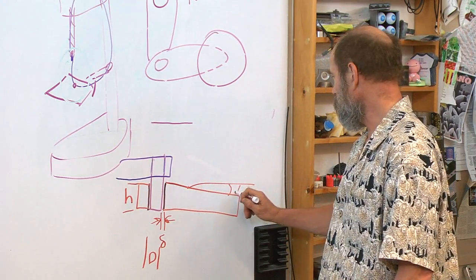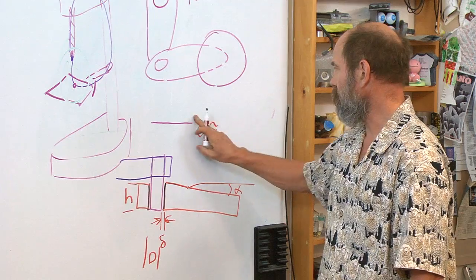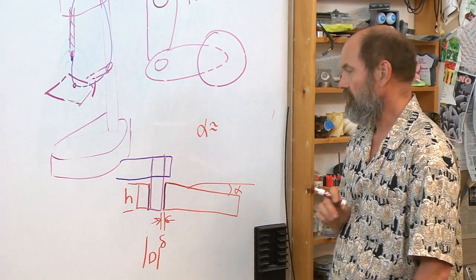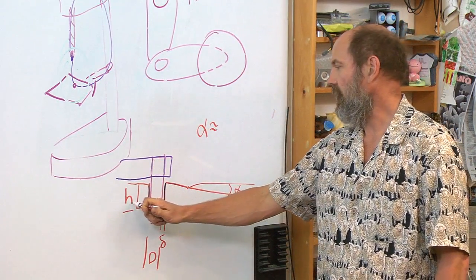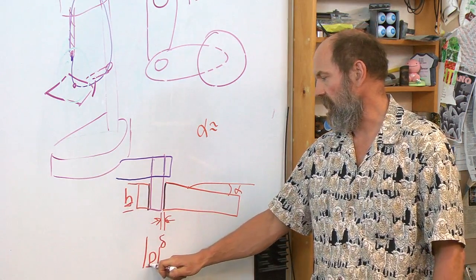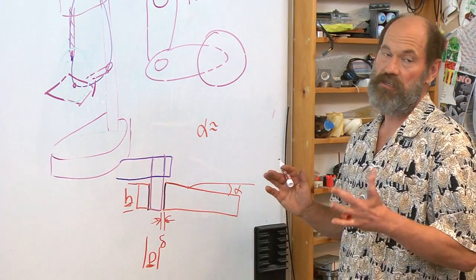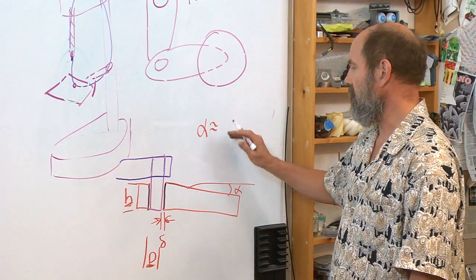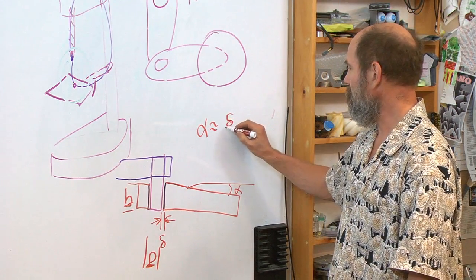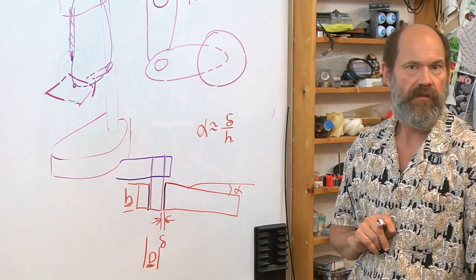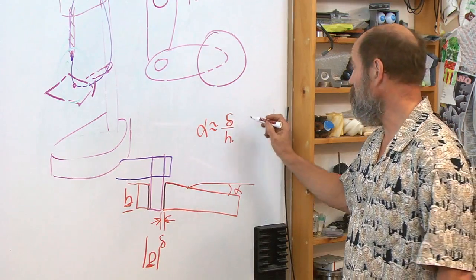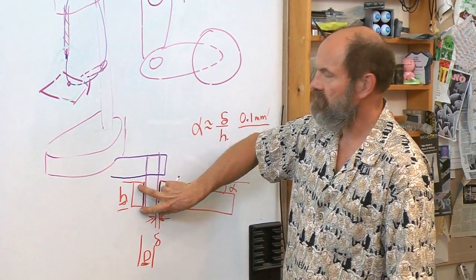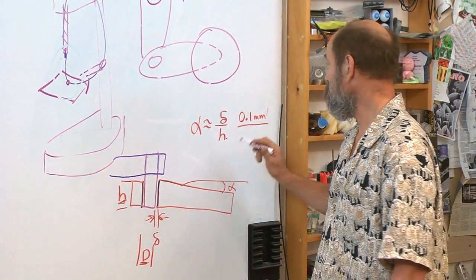Does that matter? The angle alpha, to the first order, and we'll assume a small angle approximation here, is going to be what? Very rough approximation: if this height is much larger than this diameter, by a factor of 1.6 to 3, for example, and you're going to see where those special numbers come from, then we can first order approximate this angle alpha as around delta over h. Delta may be, for reasonable things, 0.1 millimeters. H may be 50 millimeters.